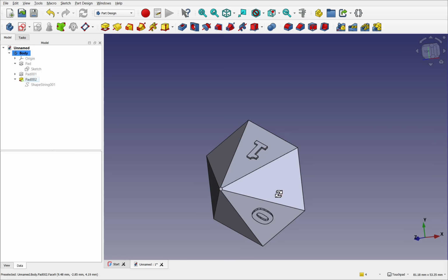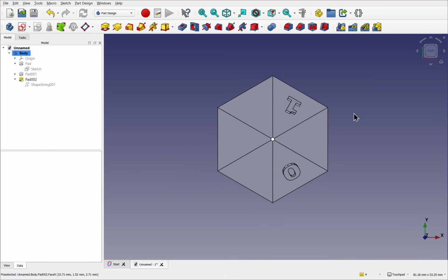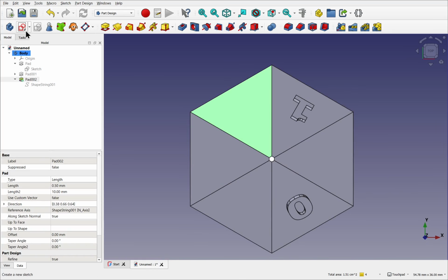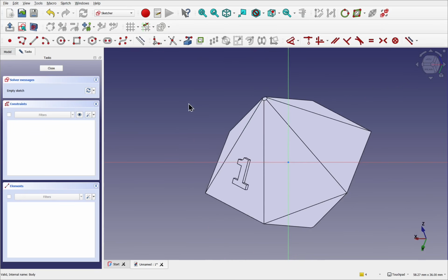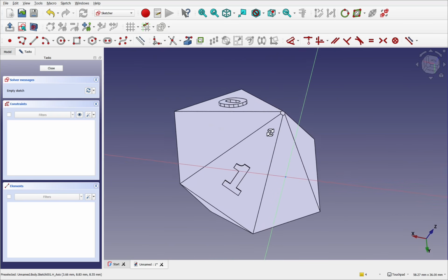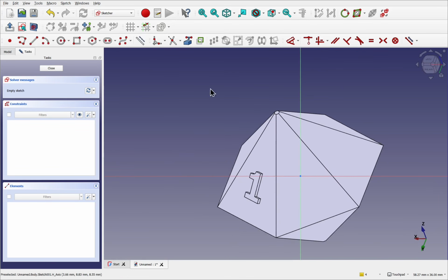Let's see how this differs from a sketch. First of all, let's take something like the top view and have a look to see what we got. When we add a sketch, we select one of the faces and then click Add Sketch. You can see the alignment of this face. The sketch has been placed upon it and the face is at an angle. If I move this, then it can be quite hard to align this with my view. This is where the top button here, the View Sketch, comes into play. Clicking that, it aligns it with our view.